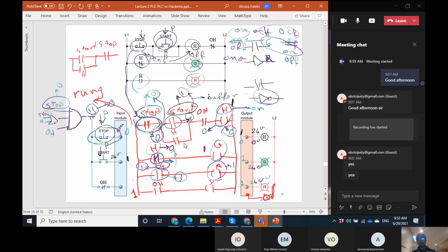And even regarding whether we need an external device: we know that sensors or switches, coils and lights are outside of the PLC. But for some of the variables, like this auxiliary contact, we should decide whether we need them or not. In this case, we don't need them.